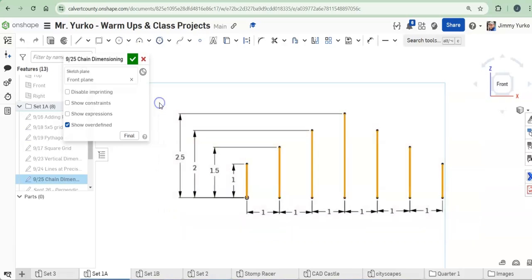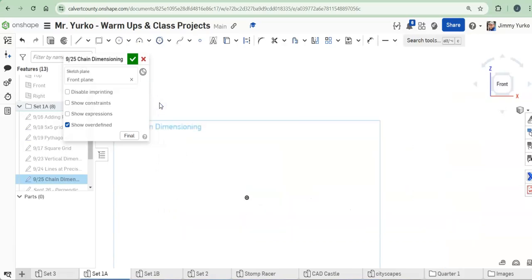So I'm going to go ahead and delete all those, and we're going to just construct some new lines. So starting on the origin, I've got a vertical line. You can see that the line constraint symbol is popping up to the right of my line. So if I click now, I will get that. Remember to end the line, just double click. So double click, and now I can move on to the next one.